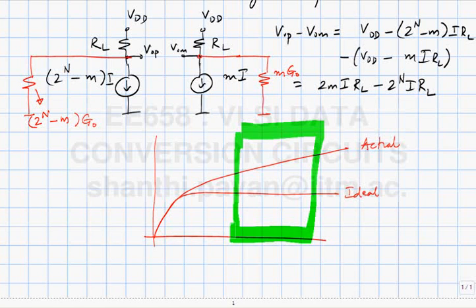In practice, the MOSFET, those of you who have taken the MOS modeling class probably know that as you keep increasing the VDS, the slope of this line, which we nicely assume to be 1 over lambda I, is not really as constant as you would like it to be. The so-called equivalent small signal resistance of the current source is not constant with voltage. It keeps changing. So, to that extent, stuff will be in error, right?